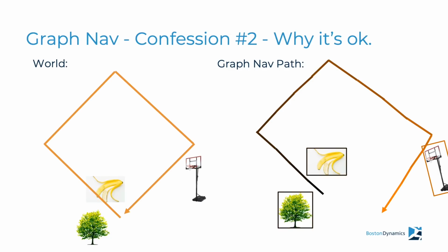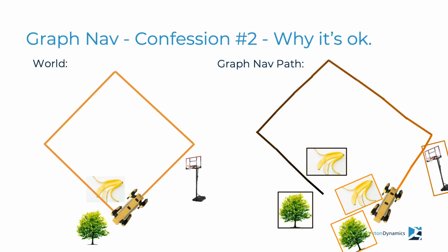So the black part of the path is the start, and all the features that you record at the start of the path are going to be black. When the robot gets to the end of the path, it's going to resave those same features again at a different geometric position and a different path length. What this allows us to do is at playback time, when we go to localize, we are localizing to the features that we recorded when we were back at that region, which means that even if the system drifts, we have multiple copies of the same feature in the map, and we can just localize to the ones that were recorded when the robot was actually at this position in the map, not at the ones where the robot was at the position at the start of the map.